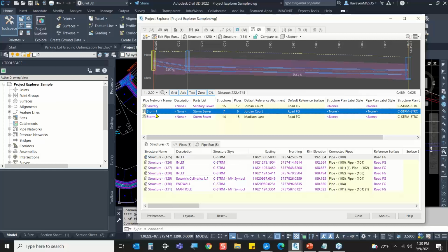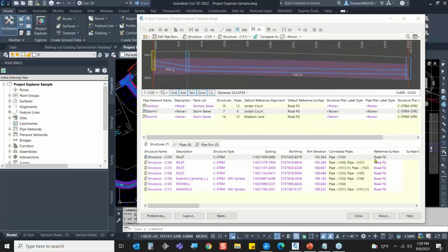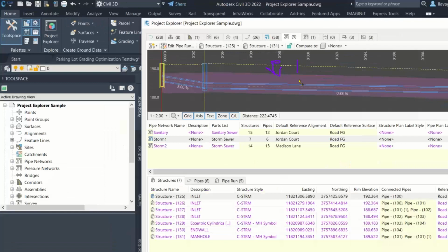Once again, if it's bold or that purple color there, it is editable. This box and interface is completely editable. The colors that you see here, the shadings that you see here, the order that these columns are at, if you don't like them, this can all be reorganized and restructured to fit your needs. And inside of here, immediately I can see that on screen, you see that purple? That's my rule set. You know how typically we end up taking existing ground to try to create a minimum or maximum cover? That's my rule set, and I can immediately see on screen whether that rule set's being obeyed without having to create minimum depth profiles or take the surface and copy it down. Bang, immediately you see there on the screen.